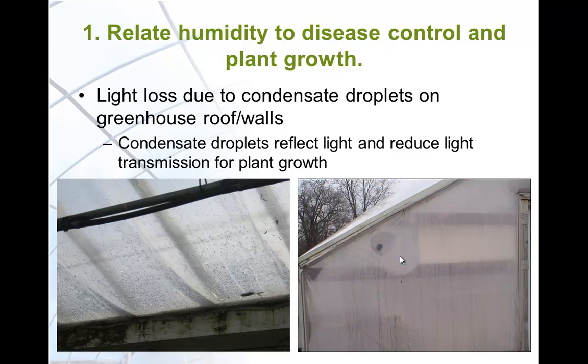For growers using inside air, that's air inside of a greenhouse space, to inflate the double poly, it is more problematic, because greenhouse air is typically warmer and higher humidity. Pumping that air in between 2 layers results in a larger amount of condensate. It is better to use outside air to inflate double poly. Outside air is typically cooler, but has less humidity, and less condensate will form.